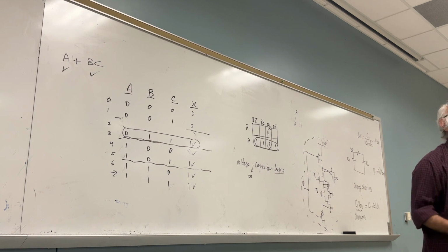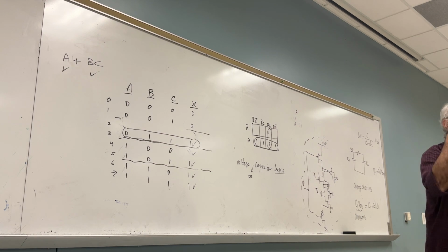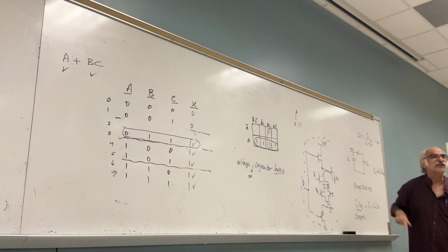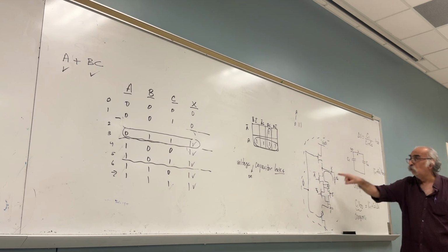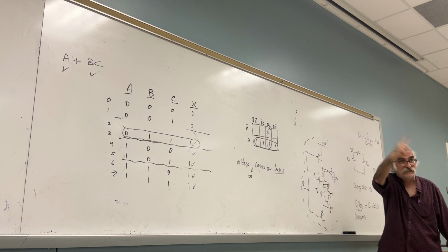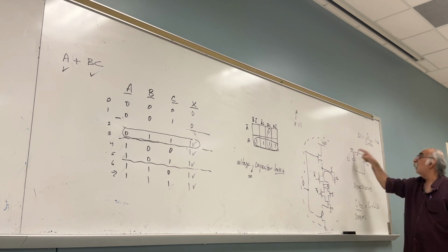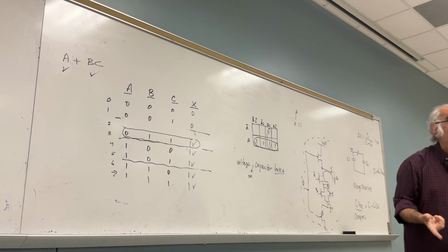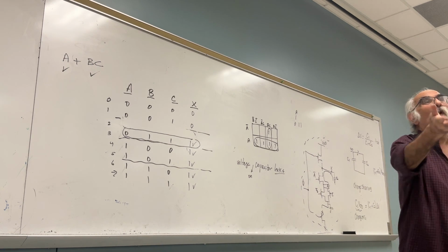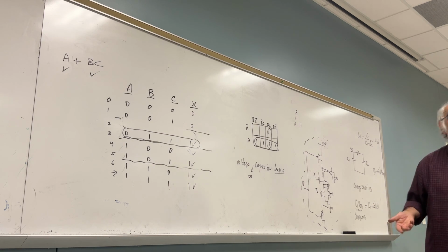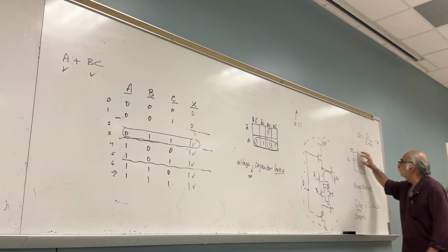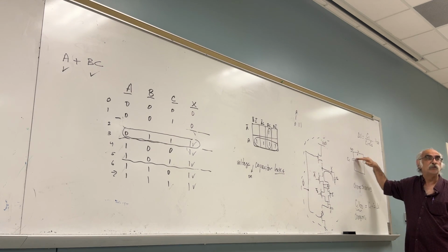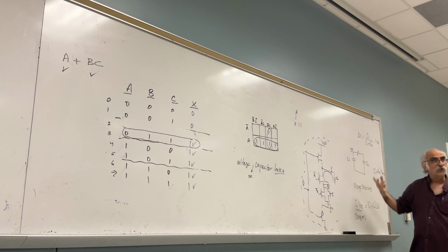Is this what you are telling me? Yes. I agree. All I'm saying is that B1 and B2 are not the same. But when the switch closes, the voltage has to be what? The same, because they are in parallel. What happened to C1? It drops. Part of the charge here is shared with this one, until the voltage is the same between each one of them. Did you get it or not?